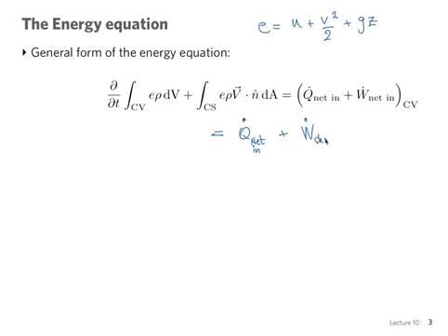So we write the shaft work to indicate rotating machinery, pumps or turbines, and the pressure work. For the pressure work, we derived at the end of last class what it would look like: it is an integral across the control surfaces of pressure, V dot N, the outward unit normal, and differential of area.